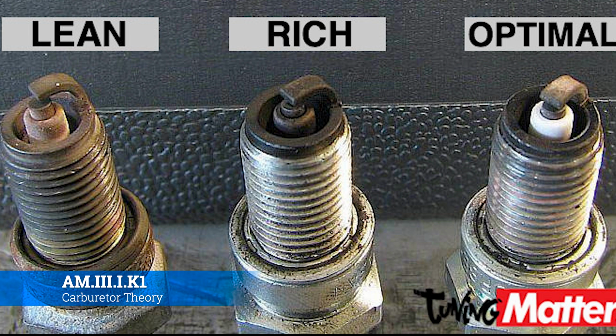Whenever it's running too rich, a lot of that soot ends up on your spark plug, just like you see here. You can see on the right, a running spark plug, and then a super lean one on the left hand side, and in the middle is this overly rich engine that leaves a bunch of trash on the spark plug.